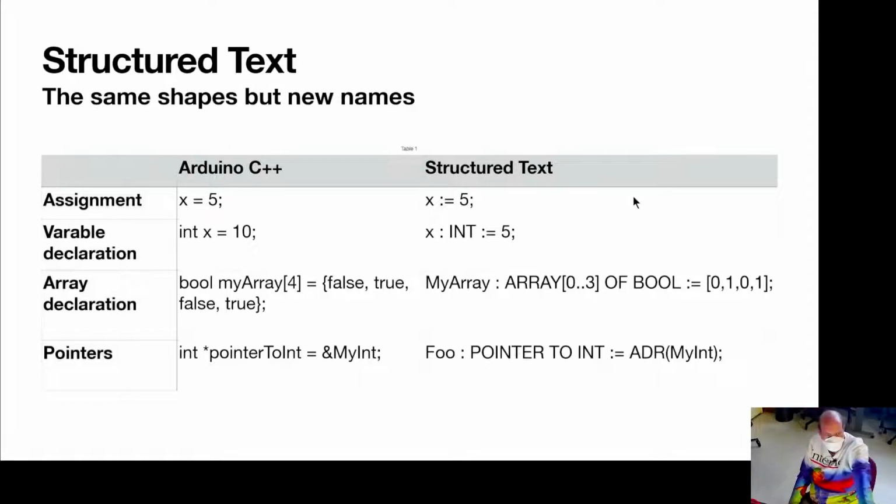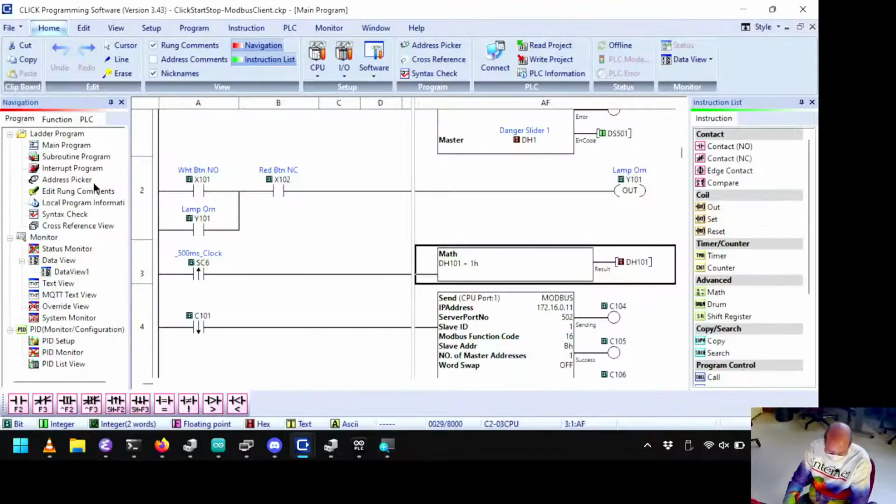We have a question here at the iPad. We do. Does each Modbus TCP device have a separate address, or can you put a bunch of them on one IP on different ports? When you configure your Modbus communication, you configure which network adapter it will do that communication on.